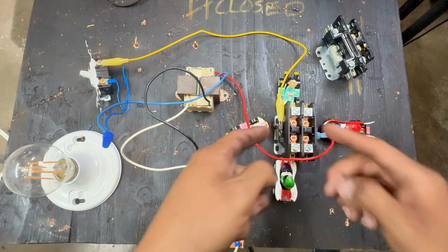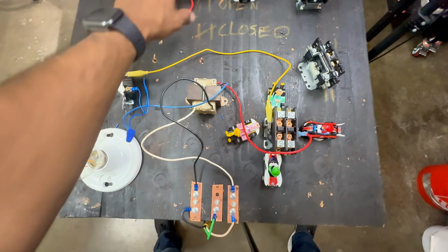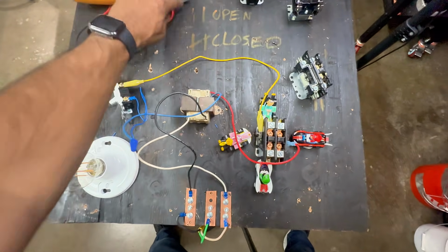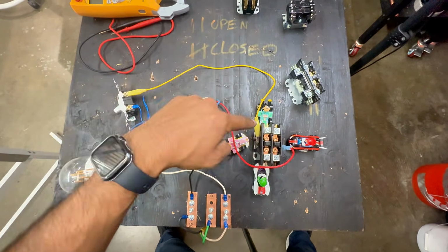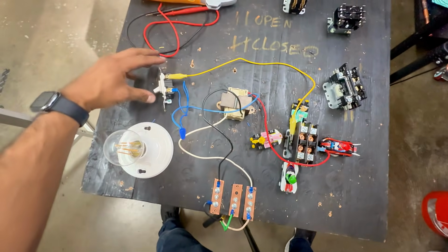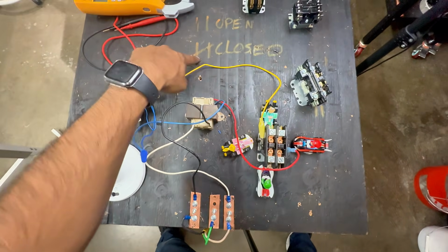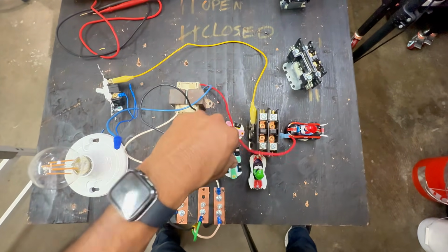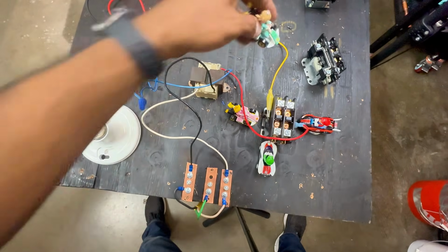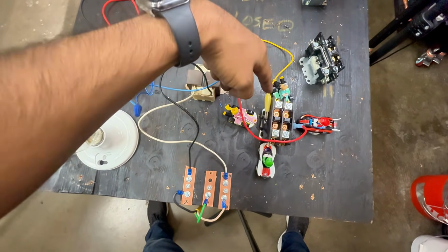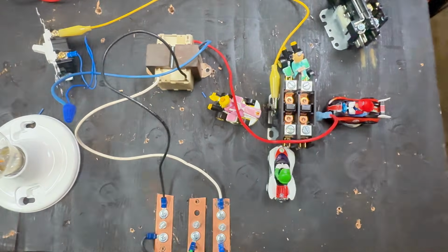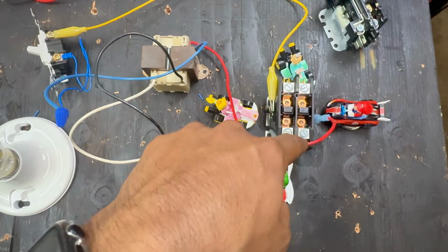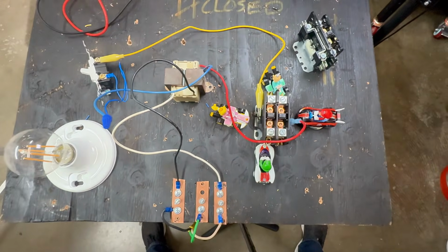And right now, you can see it right there, we just went from open. Let's open it. So on the schematic, keep an eye on this, okay? For the contactor, that's open. I'm going to send 24 volts. Boom, closed. Because now Rosalinda is with Luigi. Now I have a path from here to here. So we're using low voltage to close the bridge, so power can go from here to here. That's all we're doing with contactors and relays.